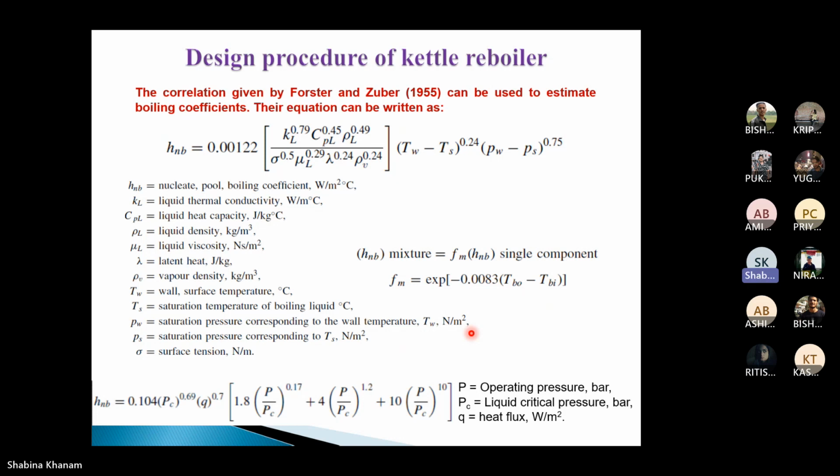So in this way, you can find out the heat transfer coefficient of the shell side. The tube side heat transfer coefficient, how will you find it? Because on the tube side, condensation of steam is occurring. If you are using steam or any other vapor, that should be condensing, so you need to consider condensation in a horizontally placed tube.